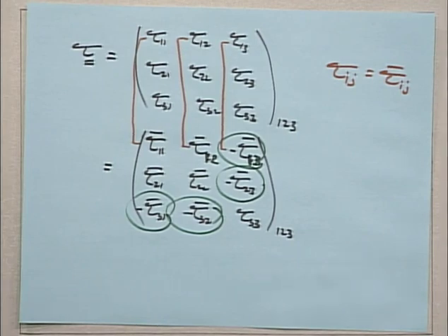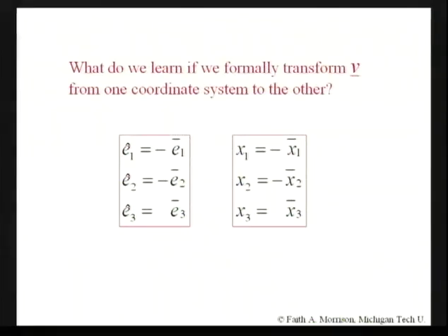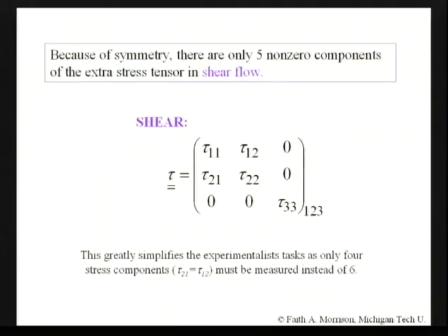Tricky and nice. So here is that summary on the printed out slides. We took the transformation of the matrices. We did the symmetry calculation, and we found that without putting the sample into the instrument, we already know that 4 of the stress components are 0. That's the advantage of this choice of flow. We only need to measure 1 shear stress, not 2, and 3 normal stresses.